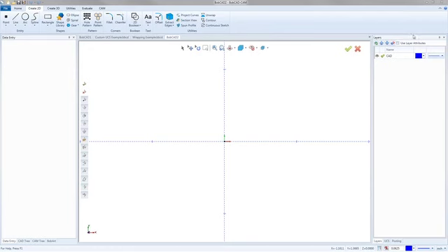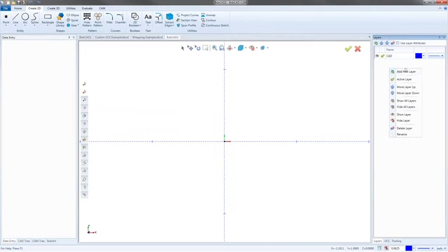So right here's the layers. We have these buttons up at the top now. So not just creating layers by right clicking like we used to. If you want to, you can. So you just right click inside the layer box, and in here you have the add new layer function. You have the active layer, which is going to let you move the active layer around. You can move layers up and down, which is something you couldn't do in the past, just to reorganize.